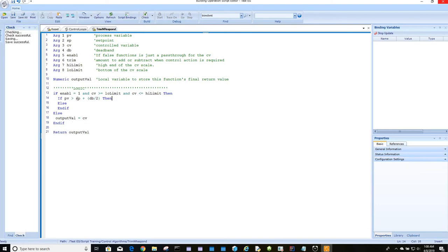So now this is saying if our process variable, in this case it would not be a sensor, it would actually be the max or the average. You'll have to play with those values. In this case I'm using the maximum because it's easier to debug, of the zone damper positions.